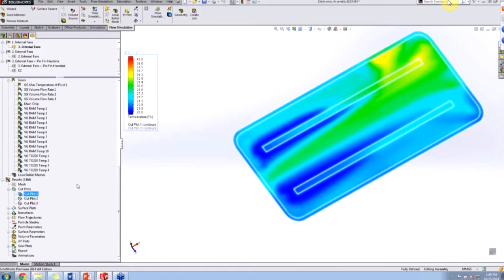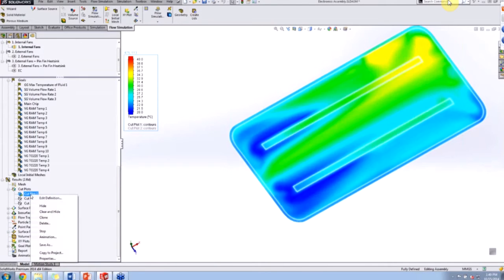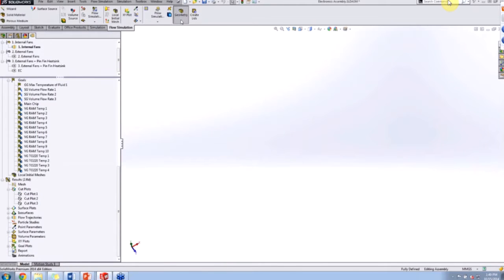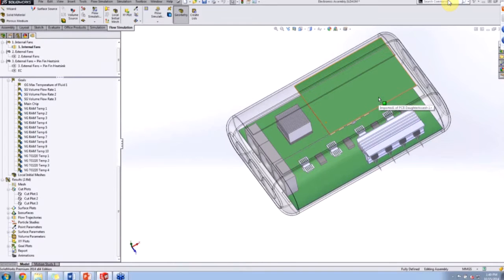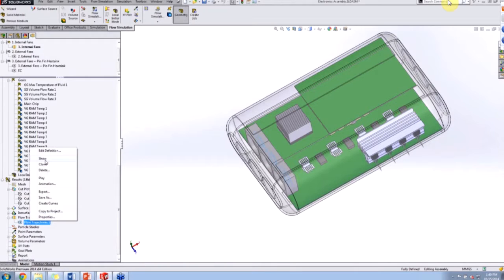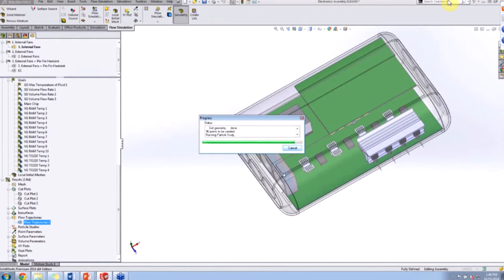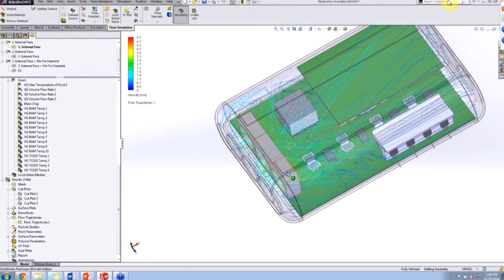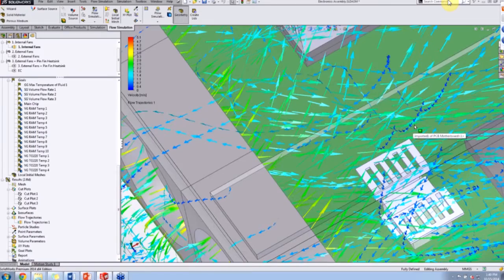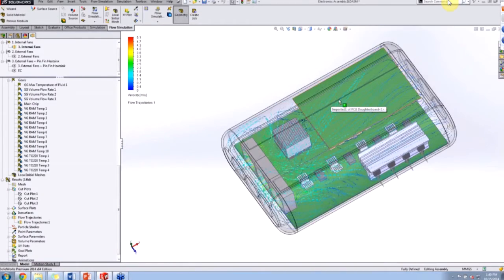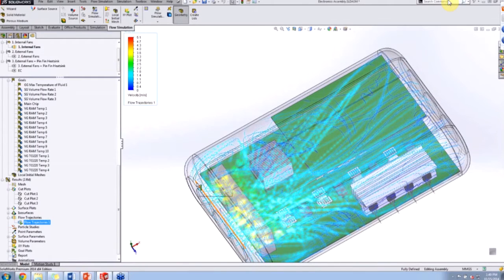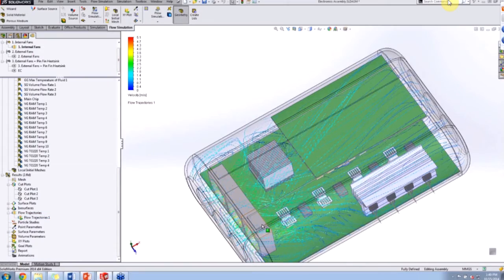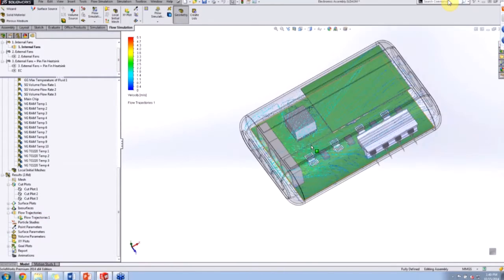At this point, you can use this and ask, is it reaching a maximum temperature where it's not fulfilling my design constraints? And lastly, since we're using an internal flow here, to see what the flow is going through the body, we can turn on our flow trajectories here, right? Show that flow, the direction in which those trajectories are going. If I zoom in a bit, you can see the vectors going in and doing this roll effect. What's really great about this is we can animate this as well, and physically see how flow is going into the body and how things are circulating around.